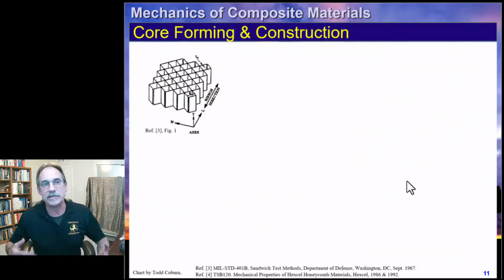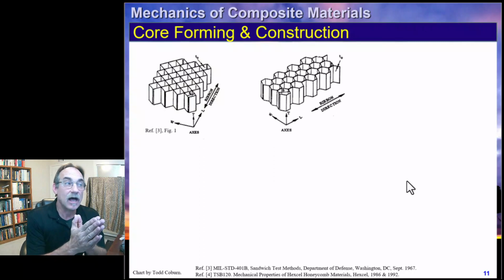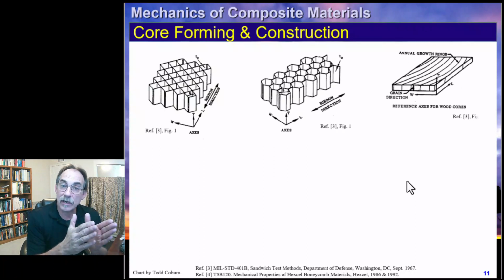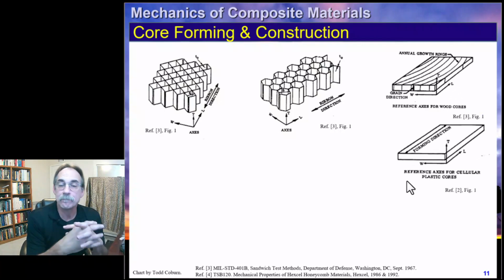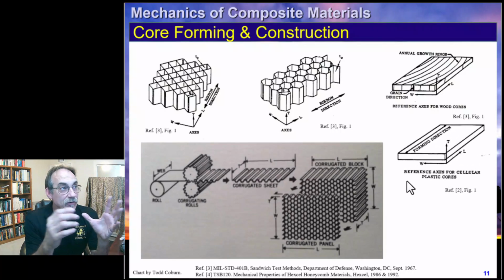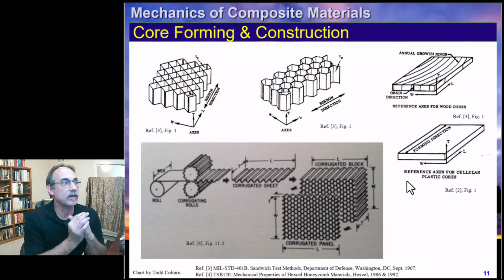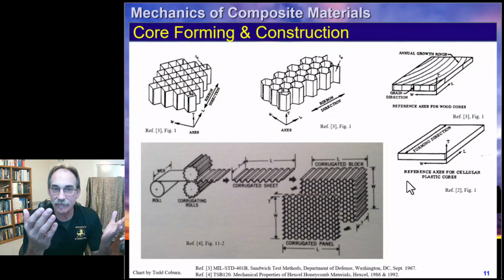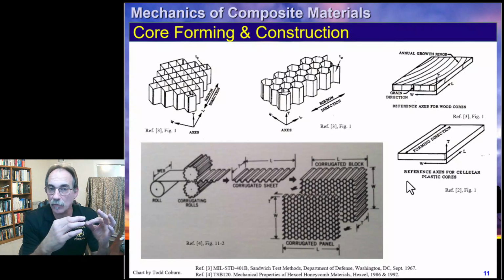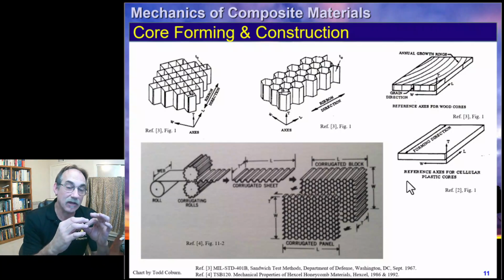For example, core materials can be honeycomb, which is very common. There are different kinds of corrugated cores. You can build truss-like structures in there, and you can use foam materials. But one common material is these honeycomb materials, which are generally formed by thin sheets. Often it can be aluminum, it can also be Nomex, or just about a number of other materials.